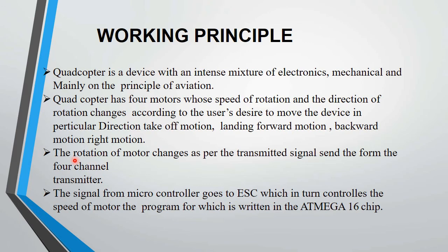The rotation of the motors changes as per the signal sent from a 4-channel transmitter. The signal from the microcontroller goes to the ESC, which in turn controls the speed of the motor, the program for which is written in the ATmega16 chip.